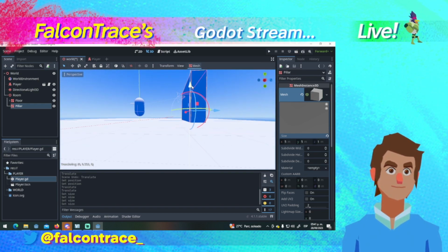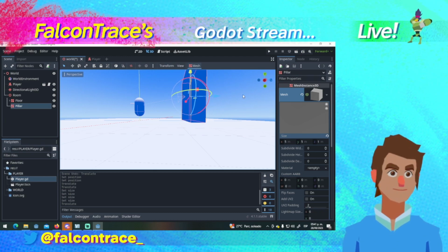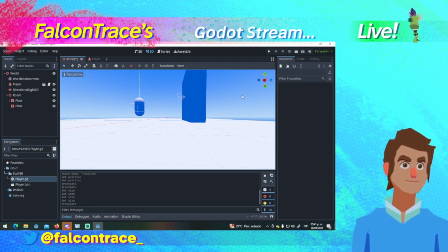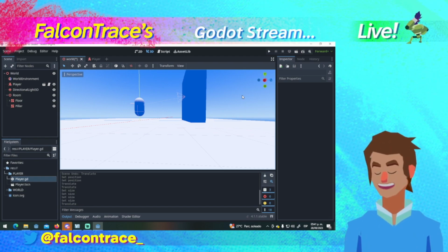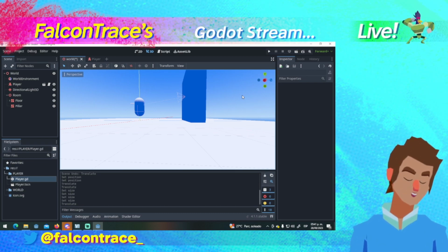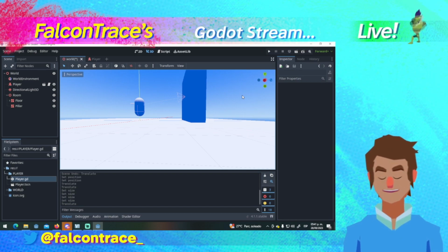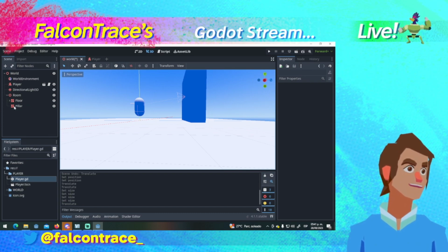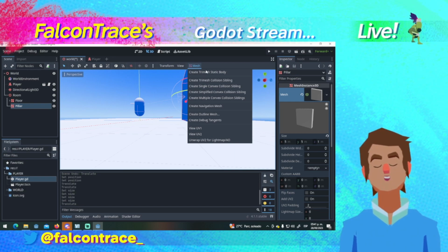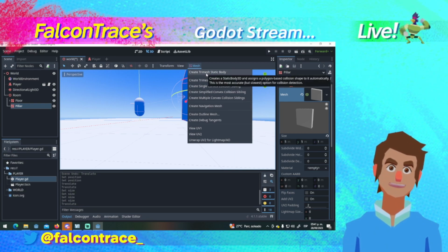Okay, so I'm going to raise it a little bit more. That's all right. Okay. Now guys, for example, we are going to give it a collision shape. If you remember guys, collision shapes are important for telling our engine where objects are going to collide. So we select the pillar and then we select mesh. Over here guys, we have different options to generate the collision shape.